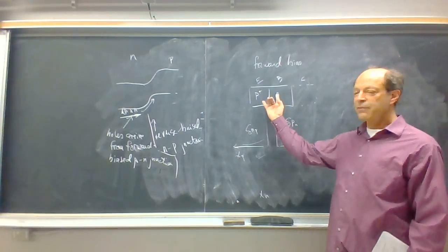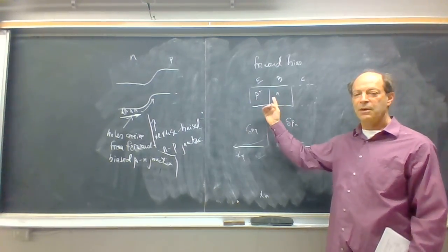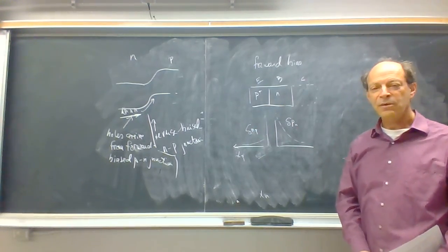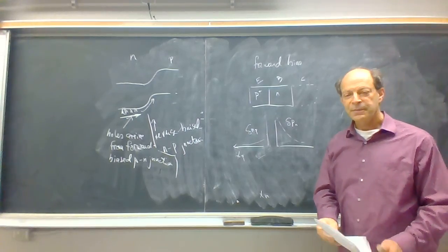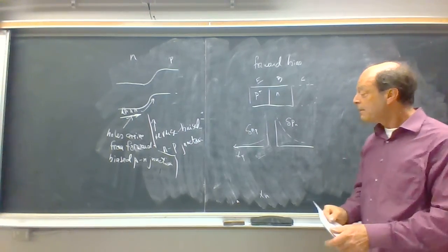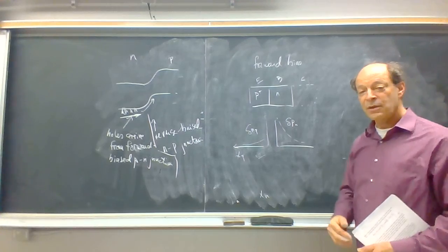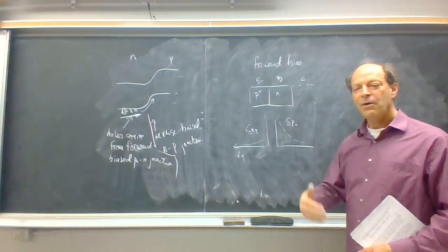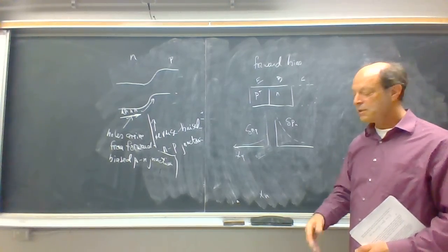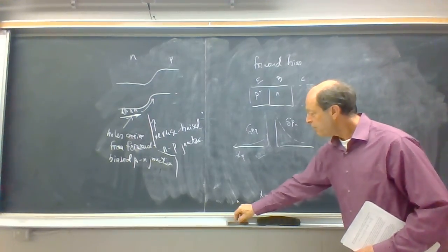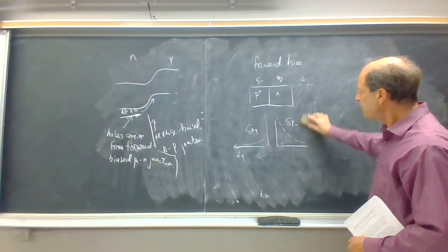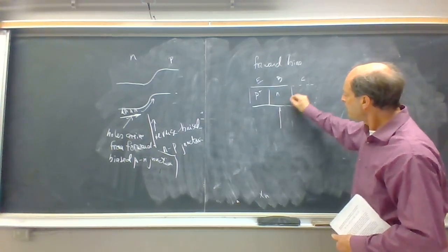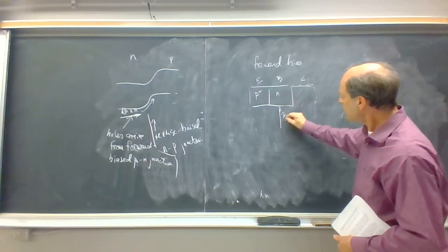By having a couple of orders of magnitude higher P doping than N doping, we can restrict this unwanted current to about 1% or less of the total emitter current. Now, the other interesting thing is I mentioned that a transistor can actually give you current amplification, not just voltage amplification. And to provide current amplification, what we would do is think about controlling the transistor through the base.